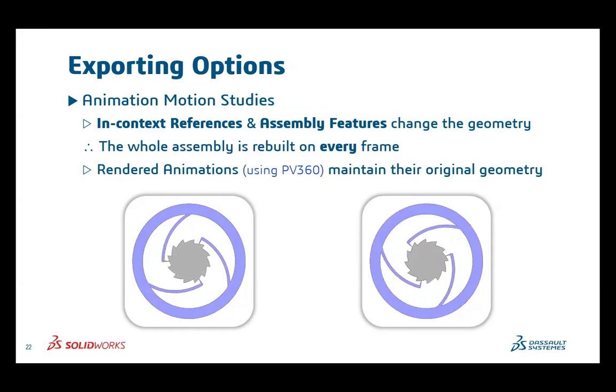It's only going to stick to the very first frame and render the whole animation with the model in that shape of the geometry. It's not going to support multiple ones. So if you save or export the animation with SolidWorks, with the SolidWorks screen as the renderer, only in that case would you actually be able to show it being rebuilt on every single frame.